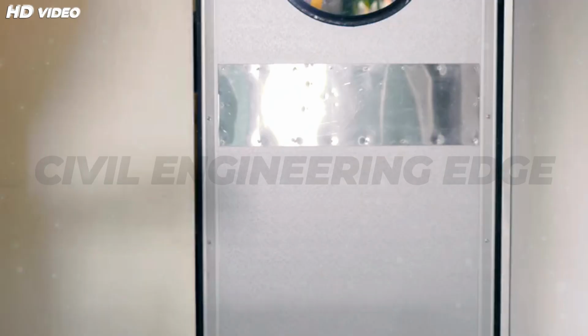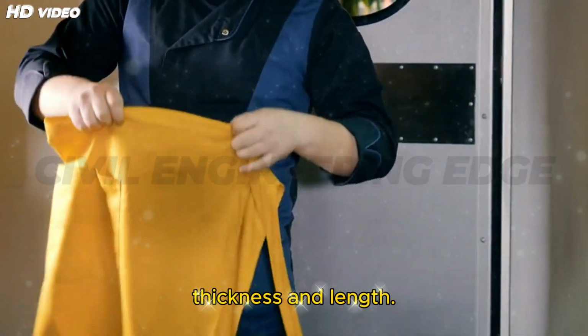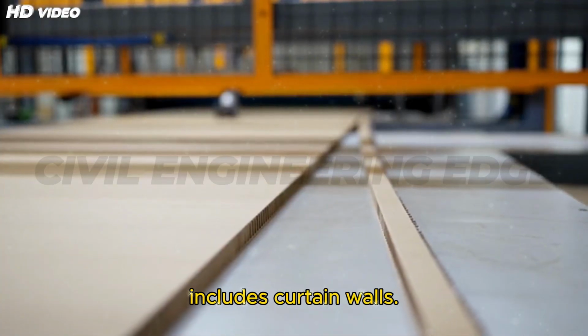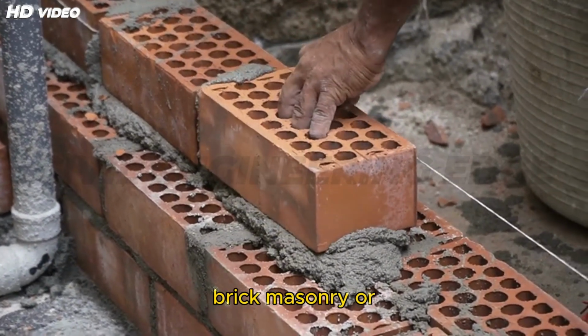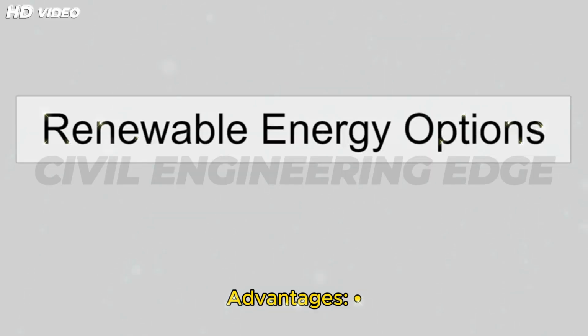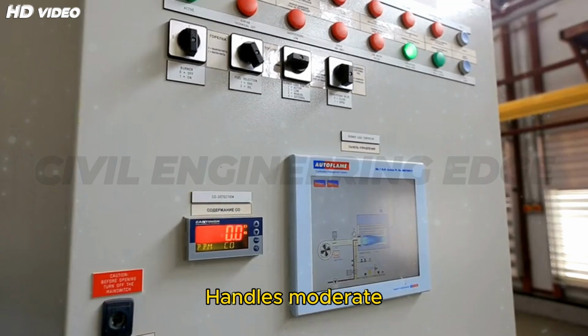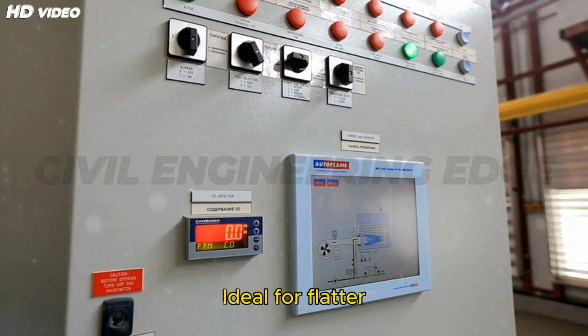Apron design: the stilling apron is provided with proper thickness and length. Floor protection includes curtain walls. Materials: mostly brick masonry or RCC is used for cost and durability. Advantages: simple and quick to construct. Handles moderate discharges. Reduces energy loss efficiently. Ideal for flatter areas in plains.